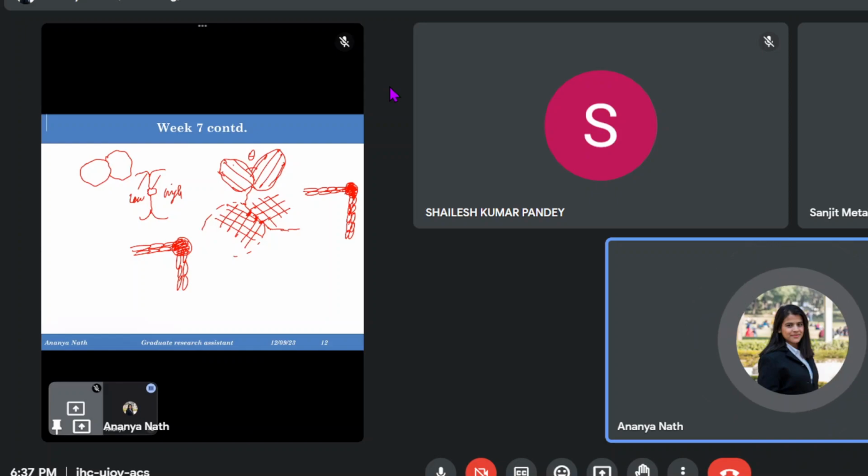Inside an old grain, if some grains are forming, in most of the cases they are equiaxed, because out of a big region, some small regions are getting formed. Equiaxed grains are very uniform with each other, and their mismatch is also like that. The high angle boundaries are making those small grains, so it will preferably be equiaxed. But about the shear bands, I'm not sure whether they are forming equiaxed grains, or just forming new grains which we cannot say will be equiaxed.